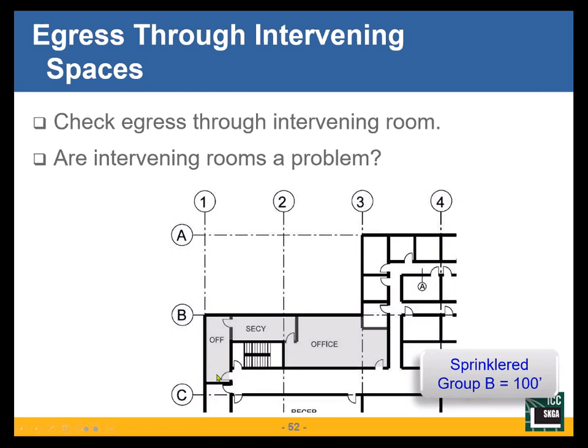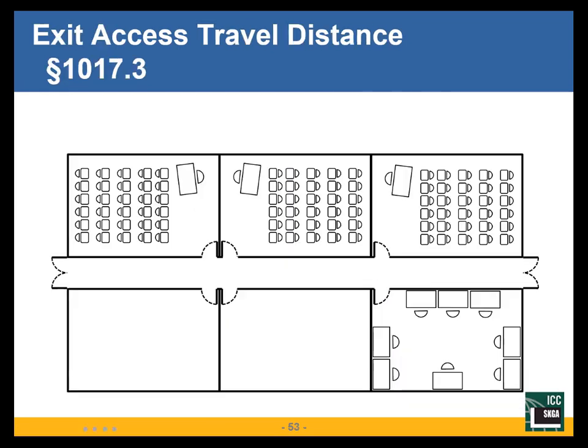It only requires one door. It can swing in. Now, this is my required exit. This is just an additional exit. So then when I'm looking at my common path of egress travel, I measure from here to here. I've complied. So there's several different ways that the issue can be solved, up to the designer.